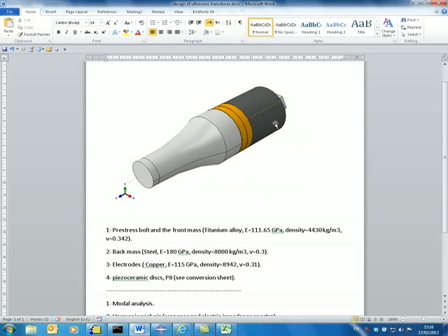during the operation. So in general, a sonic transducer is excited by electrical potential energy, and then by vibrating at the same frequency as the excitation, the piezoelectric material will generate a mechanical wave which propagates through the front and back mass.